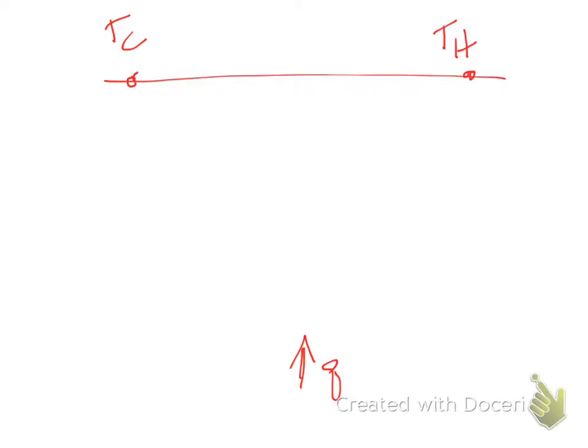So the surface is hot and cold, the same sinusoidal cycle on the surface that we just had. The only difference in this problem is we have a geothermal flux instead of a constant temperature at depth. Oh, as you get deeper, the temperature is constantly going up.